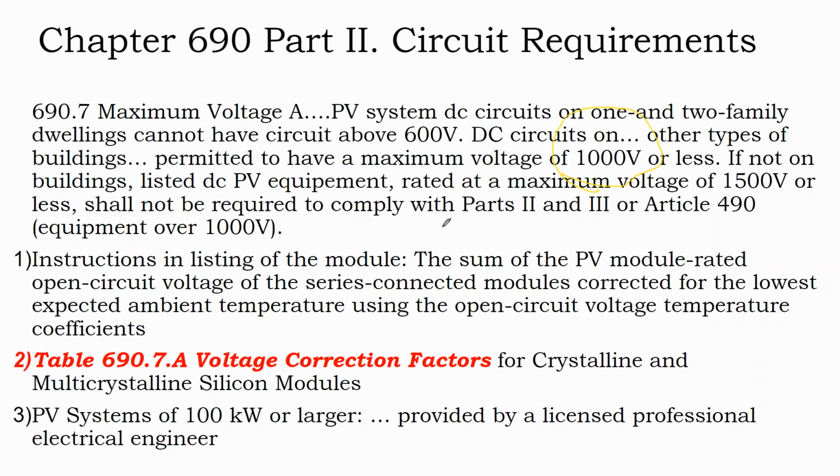And so if I'm doing a residential off-grid system and the house is in the middle of the woods and the solar array is out in the field, considering building an external battery box from the house and using a 1,000 volt platform is not bad, because then you pick up higher voltages for transmitting that electricity over a longer distance.